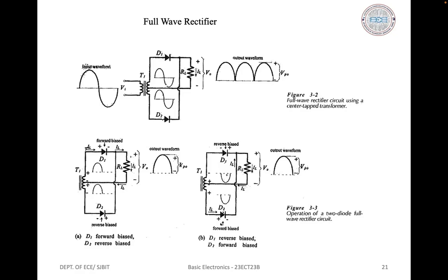of sinusoidal waveform. So this is positive full wave rectification, and if the polarity of the diodes is reversed, the output waveform is a series of sinusoidal negative half cycles, negative full wave rectification. The center tap of the transformer is normally grounded, and so the only way to obtain a negative output from this type of circuit is to reverse the diode polarity.